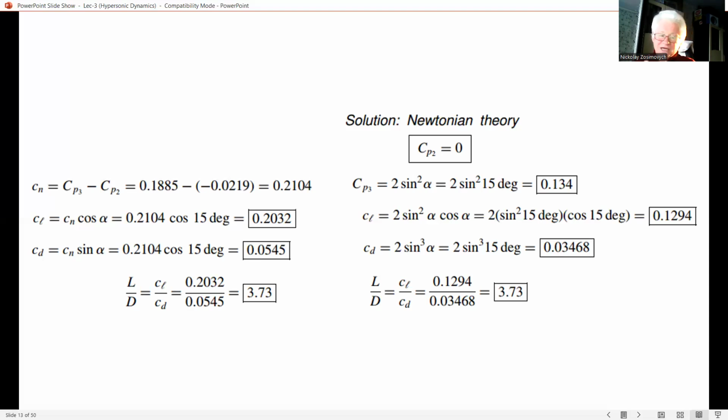To do this arithmetically, our last equation would have to be solved by trial and error. In reality, the value of 21 degrees for beta was obtained from a graphical plot of our last equation, usually called the theta-beta-M curve.